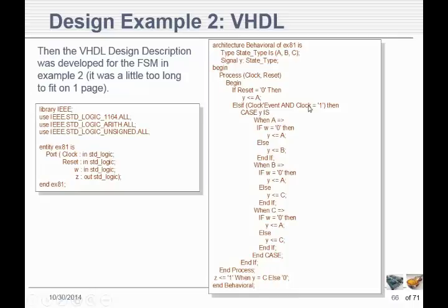It's easier to read, isn't it? Anyway, then we go by the case, and we're saying case Y. So we're looking at Y can only be A, B, or C. So if it's A, and if W is 0, then we stay in A. Else we go to B. It is so simple. To me, that is so much more simple. And I think most times I could go right from the diagram to this.